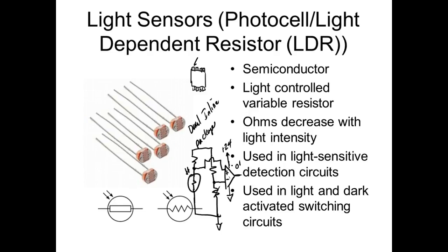Well, that's why in electronics you've got to be careful with these plus and minus symbols, because these are symbols. And what is a symbol? Representation. So on these guys, this is called a non-inverted input. This is called the inverted input. That makes sense? So if this one is greater, it's going to saturate this way. If this one's greater, it's going to saturate in the plus direction. And these are called comparators, the digital comparators.